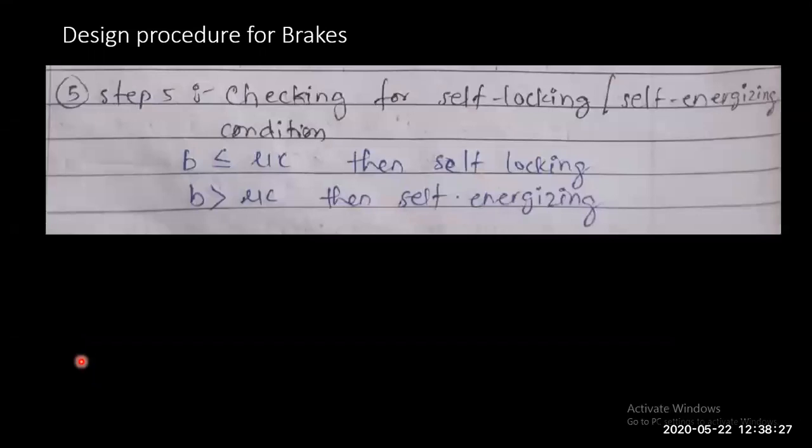Then check for self-locking or self-energizing. This condition we need to verify. Self-locking is an undesirable condition, while self-energizing is the desirable condition. You need to check whether your brake falls into this category.